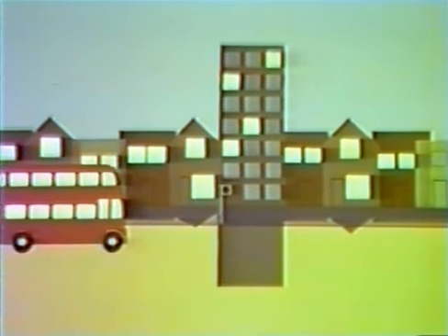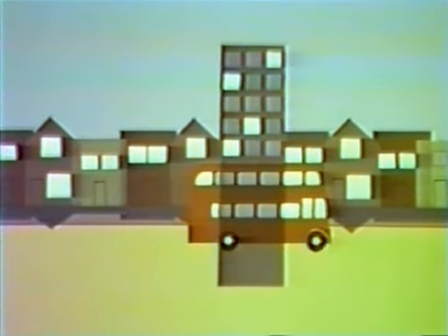This is a warmer white than on monochrome receivers, and the white must be correct not only at full brightness, but also at all levels throughout the gray scale. If this is not done, the picture of a bus, for example, which appears bright red in sunlight, would change color when the bus moved into the shade.